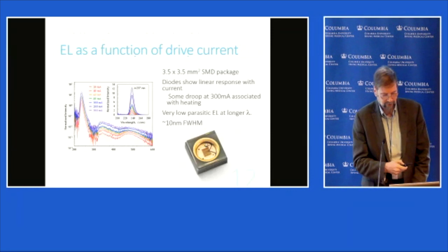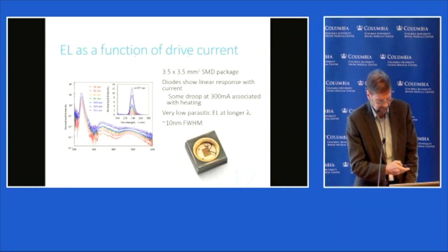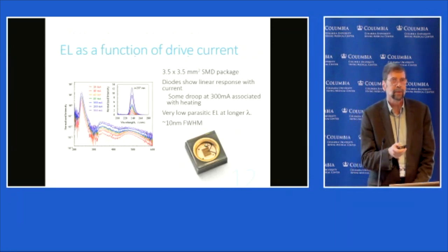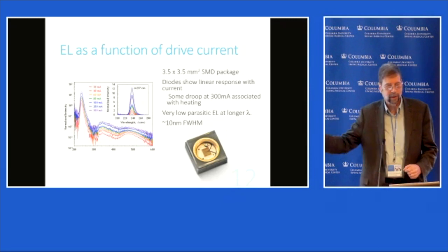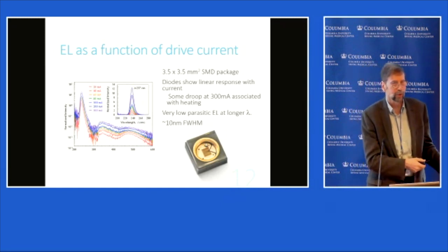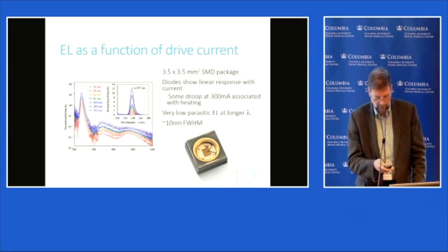And that's some of the device characteristics. One of the points I wanted to make in this was that LEDs typically have a width. So these particular ones, again, there's been new devices made that perform better, but this has about a 10 nanometer width. And that means that you'll get light that'll be longer than the wavelength you wanted, right? So you have to plan for that, either make the device much shorter or put a filter in. That's the approach that, again, Michael Kneissl's group is using.